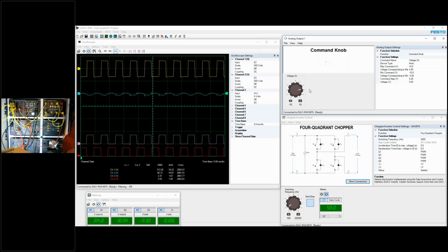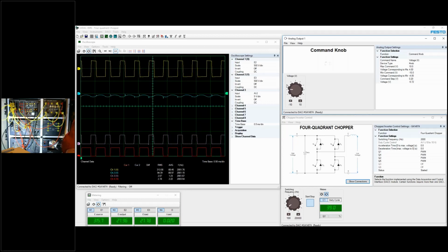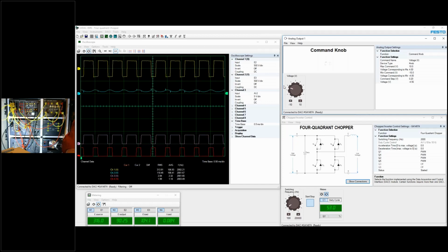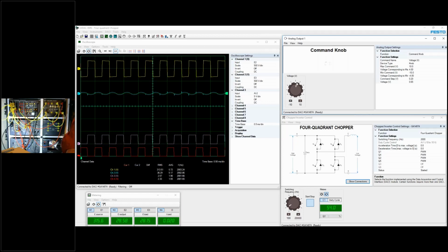negative, positive, negative, positive. So can you see that if I am able to do that quickly enough, switching from positive to negative, I should be able to produce a sine wave that will vary between -120 volt and +120 volt cyclically, generating an AC voltage at the output of a bridge that is fed DC current. And that's the next step, using a 4-quadrant chopper like that to produce AC output. And that's what I will do now.